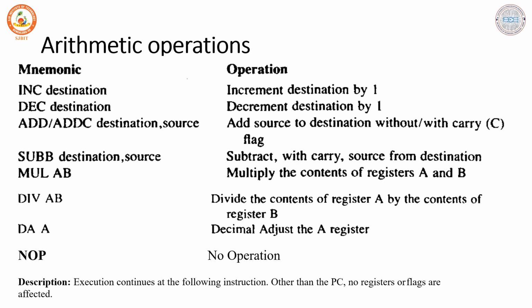And if the result is negative, then a different section of the program may be executed, right? So hence, monitoring these 1-bit flags available in the 8051 architecture, by knowing the status of the program status word which contains all these carry flags, will be used for the computation, and that can be determined, and also we can analyze the program flow control